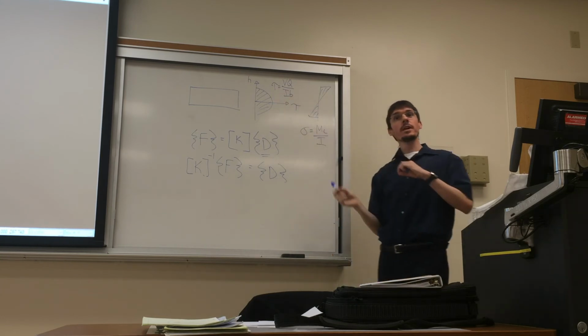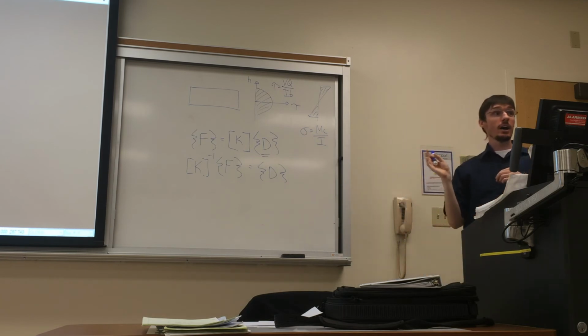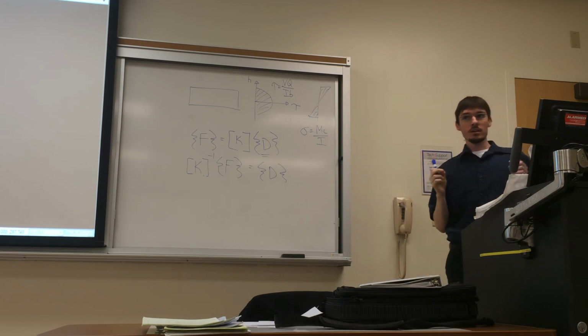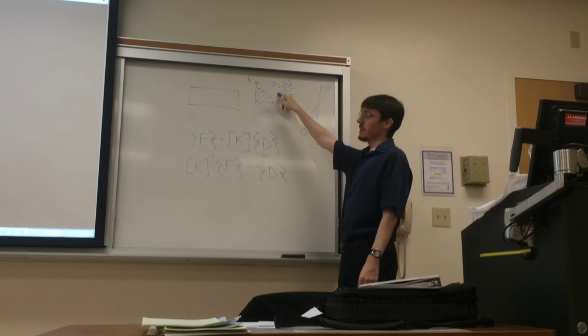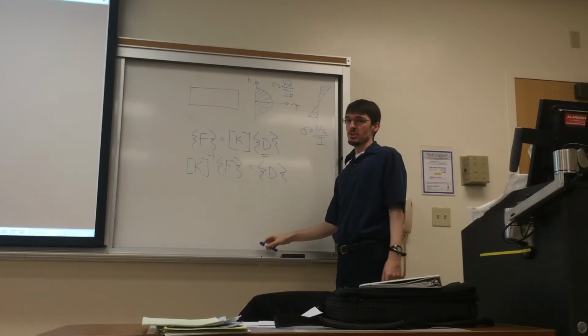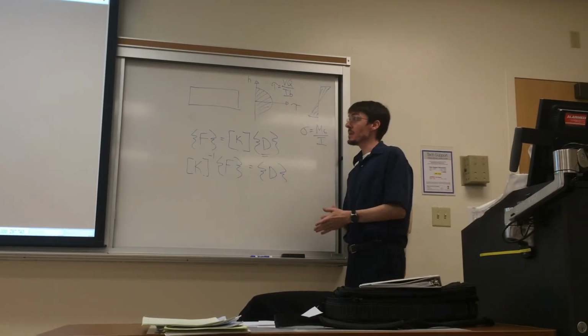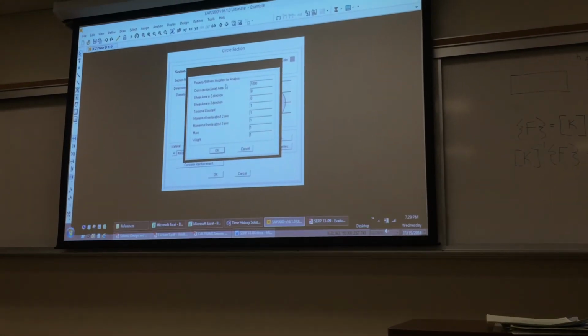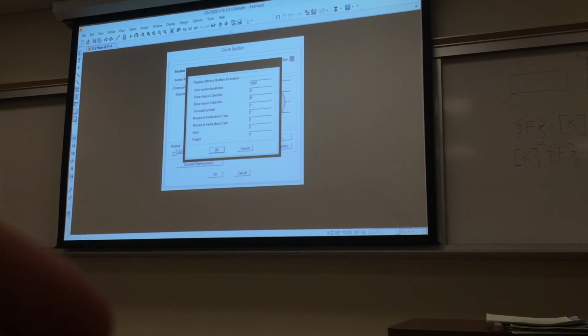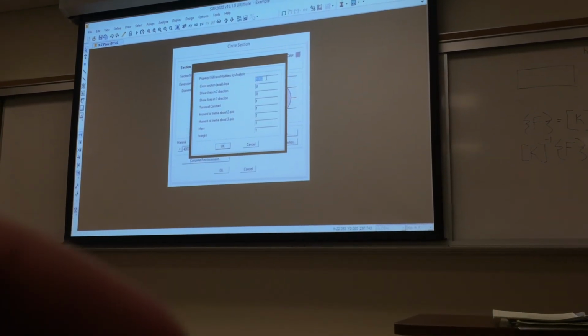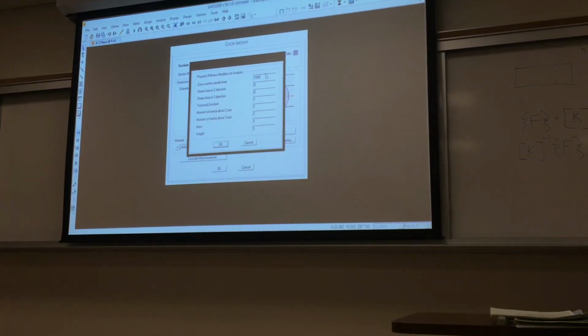So lots of little things you want to keep in mind when you're trying to play around with these values and changing things in your computer model that if you try to, let's say, shear deformations are negligible, you have to make sure that they actually are. If you have a really deep beam, they may not be. But for our problem, we're going to go ahead and ignore those. So I've made my axial stiffness now really high. I said the shear area for this is 0. So with the shear area of 0, I get no shear deformations.